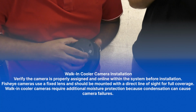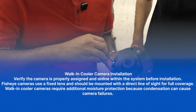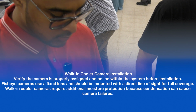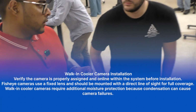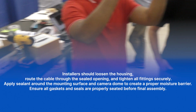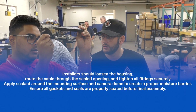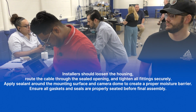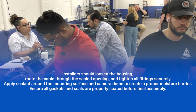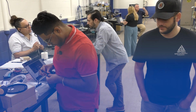Fisheye cameras use a fixed lens and should be mounted with a direct line of sight for full coverage. Walk-in cooler cameras require additional moisture protection because condensation can cause camera failures. Installers should loosen the housing, route the cable through the sealed opening, and tighten all fittings securely. Apply sealant around the mounting surface and camera dome to create a proper moisture barrier. Ensure all gaskets and seals are properly seated before final assembly.